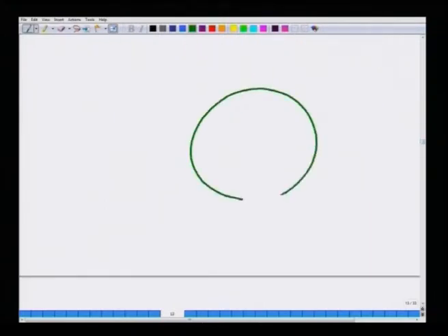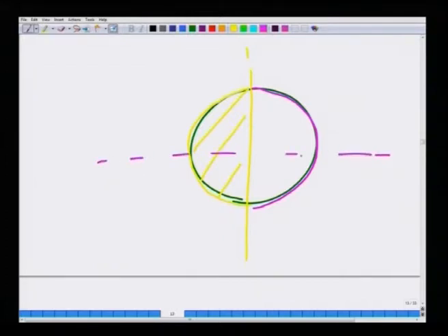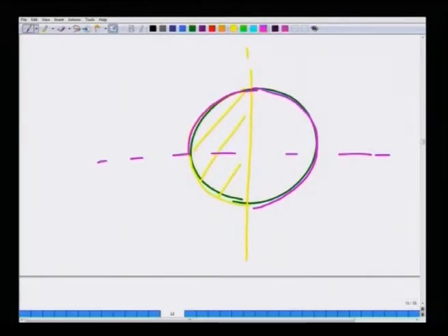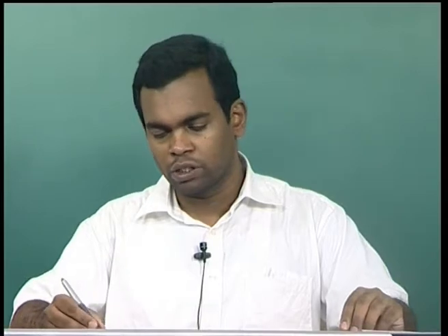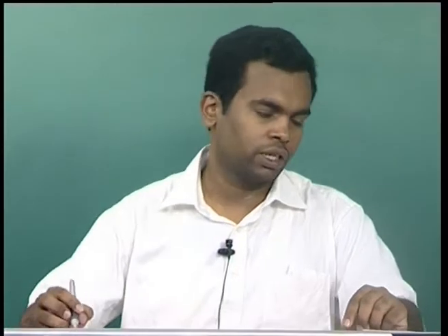What experiments are telling us is that the pressure distribution on this side of the sphere is very different from the pressure distribution on this side of the sphere. So, if you integrate the pressure distribution, you can foresee that it is actually going to be non-zero. That will give rise to a non-zero force if you use the pressure distribution found in experiments. But potential flow says that the pressure distribution is completely symmetric about the theta equals pi by 2 line. Therefore, you got a 0 answer.